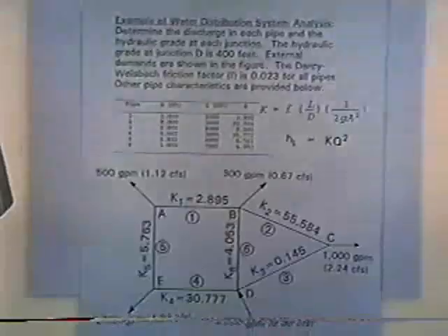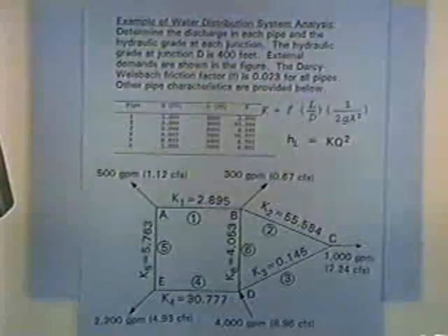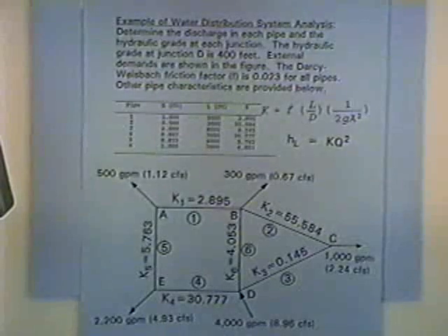And if we had valves or other fittings in the pipe, we could put the K for the minor losses right in with that K. That K could express valves and bends and contractions and so forth as well. In the example, I just use the straight section of the pipe. But from now on, the K is our expression for the loss characteristics of that section of pipe and anything that's in it.